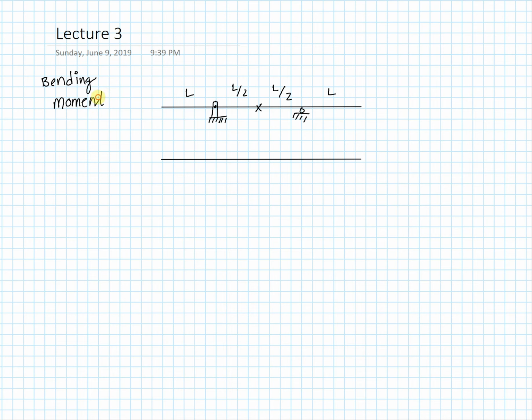So bending moment is really what we're interested in now. So with the Muller Breslav principle, it tells us that we need to introduce a hinge at the location of interest for bending moments. So we introduce a hinge like that. And when we introduce a hinge, we move it up. And we're going to draw straight lines. Going to look like that. And another one is going to look like that.